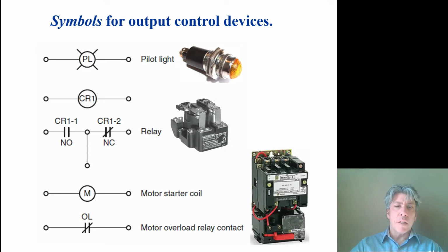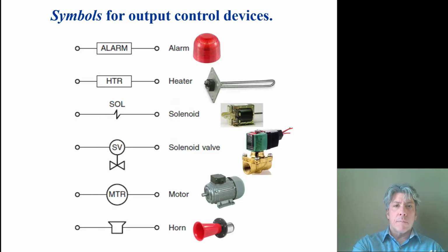So this lower motor starter coil, I would rather see the three switches that are associated with supplying power to the motor, which is typically going to be a three-phase motor, rather than just the overload switch. But the overload switch is a valid part because often the contactor and the overload are connected together and form a whole motor starter. So that's all right.